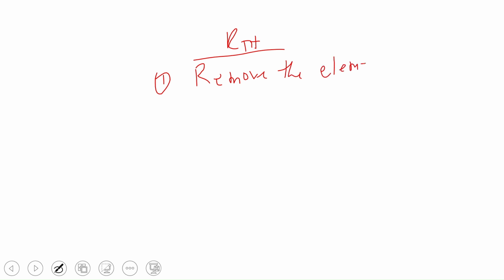Now, let's look at how we find RTH. Number 1, note that all the steps you follow to find VTH on the main problem end with VTH. Because if you are using a voltmeter, you just bring the voltmeter to do the measurement. When you finish, you are done with that circuit. What you need to do is go back to the circuit again, and though we have already removed the element, you should know that you will remove the element, the element that has already been removed. Number 2, according to Thevenin's theorem, you have to measure the resistance, but before that, remove all sources.